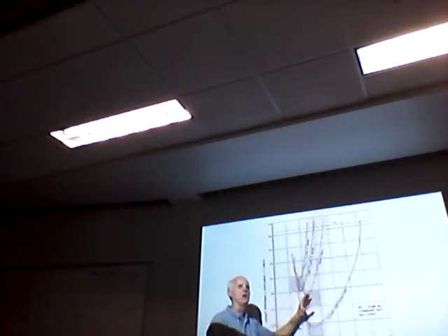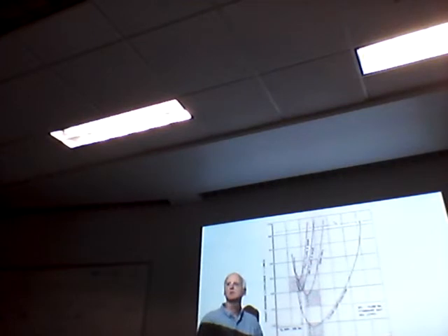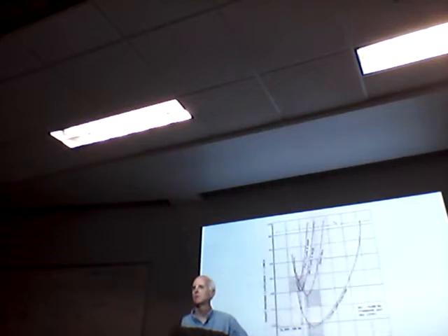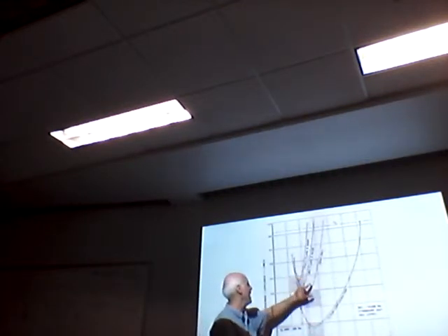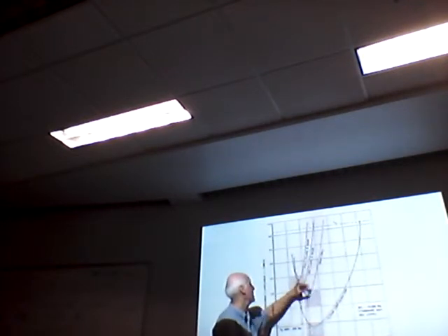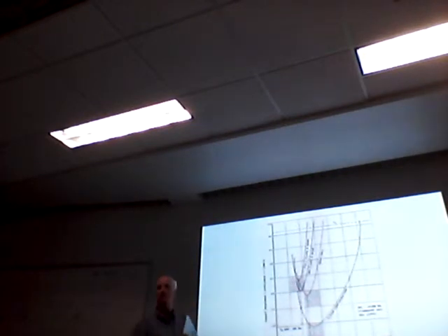So, but nonetheless, you ought to be able to tell what configuration changes do to your curve. So you've got a basic curve, and then what else happens? I can say the more you put out, the more severe it gets. Yeah, well, what's happening here? You've got flaps, and yeah, you're overcoming parasite, but you've also got induced drag increasing too. So yeah, it does get steeper there. So anyway, it's just basic relationships between configuration changes and what that does to your drag and lift.